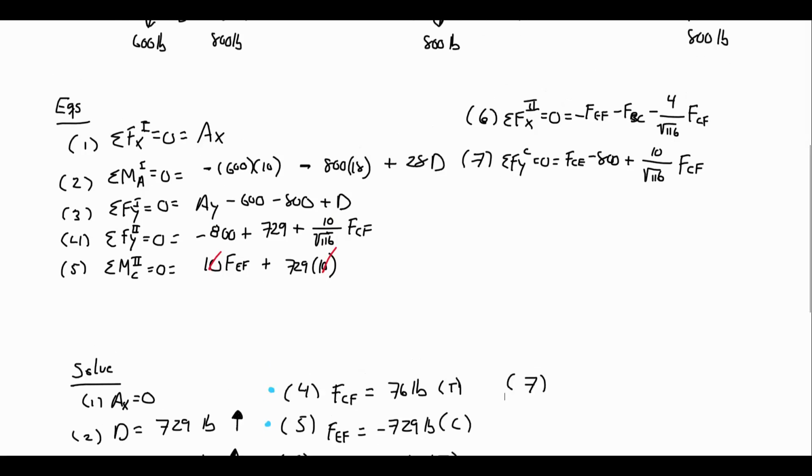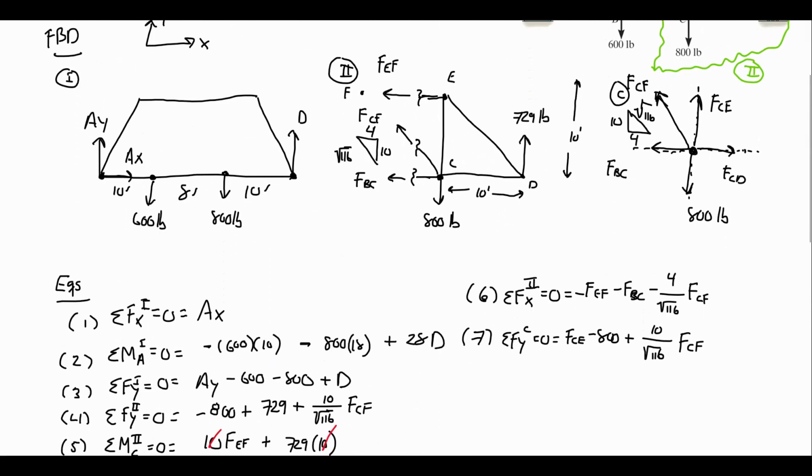I'll just point out again, when I'm writing all of my free body diagrams, those internal forces I am leaving as variables even once I know what their numeric value is. Because to be consistent of tension positive, compression negative, this is going to be the easiest way to do it, is we keep drawing them assuming tension. Even once we know that is wrong, we need to stay consistent with all of those values. So I'm always writing it in variable form in the free body diagram. I'm using that free body diagram to write my equilibrium equations. It's not until the solve step that I actually will substitute in the numeric values for ones I already know.